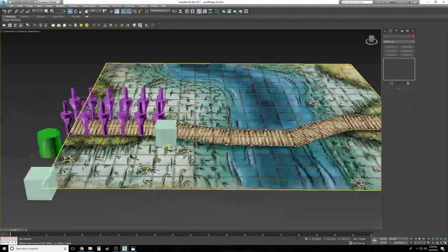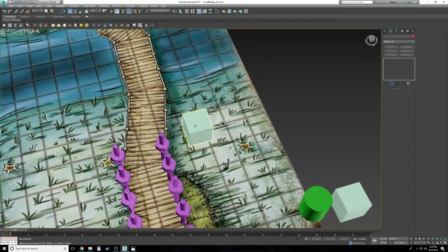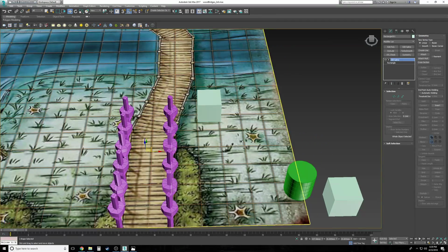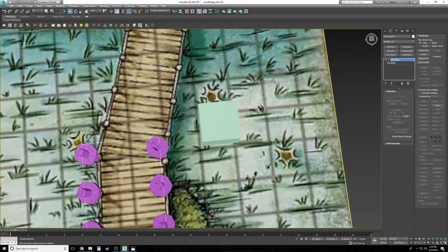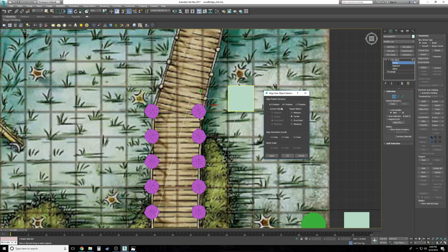All right. So basically, I wanted to have it set so that it will be an anchor point I can use to align pieces with, because I know this is going to be the top. If I look at the top, this is going to be the end point of this particular 6-inch bridge. So I want to select just these top here. I want to select the align tool, cancel out all this. And all I need to do in this case is I want to go this way.